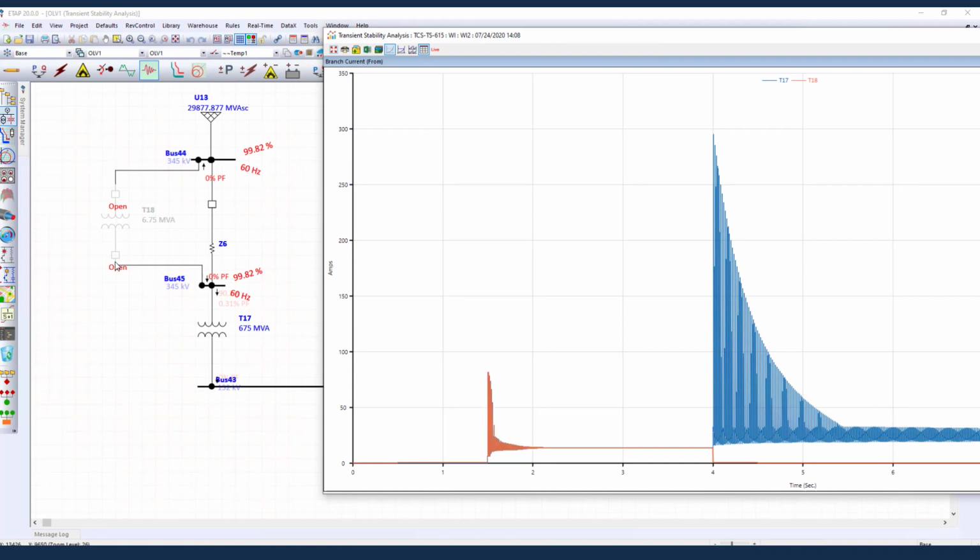You're going to see the inrush current, but because the first transformer is really small, it's going to draw very little inrush current with respect to the utility size. With respect to its own size it's still large, but with respect to the largest transformer and the utility, this current is small. Now that the first transformer is energized, we're going to energize the second transformer. Now what happens with the second transformer, because you have a very large impedance, because this transformer in terms of size is 100 times smaller, you are energizing this transformer with a very large impedance.